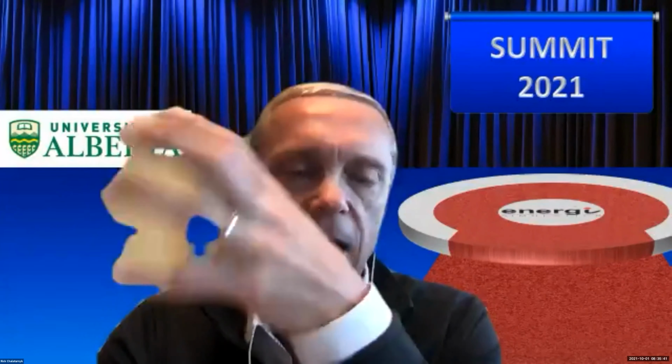True? Well, there will always be discussions and arguments about how the models are set up, all the boundary conditions, all of the uncertainty in the geology, uncertainty in the properties. So this was really that discussion around, if I'm trying to look at failure mechanisms and utilize the simulations, modeling has to be a part of it. You include pressure transients in the modeling. It will be a part of how stress is going to evolve, how deformations are going to evolve. So yeah, absolutely. And especially for CO2 injection and others, the large pressure transients are going to be really critical for things like induced seismicity. Yeah, absolutely.